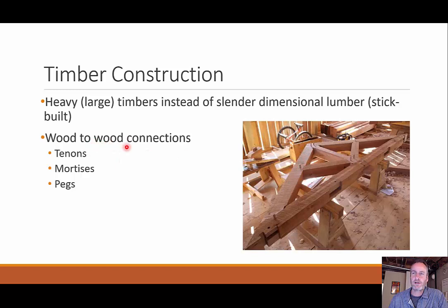It does say wood-to-wood connections. That means you're not using nails or brackets or gussets. Instead, you actually have the wood being placed inside this wood, and then you have some pegs being pushed through. I can tell that a wood member would fit in here, have a peg through here. We'll talk more about those in just a minute.